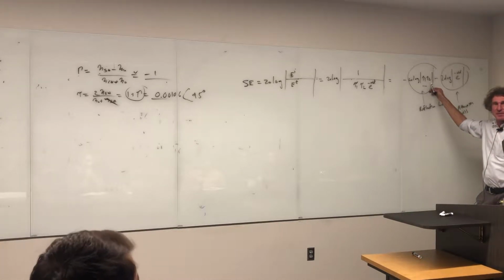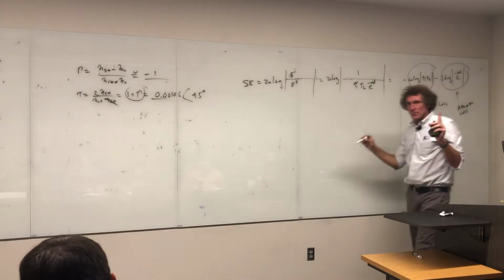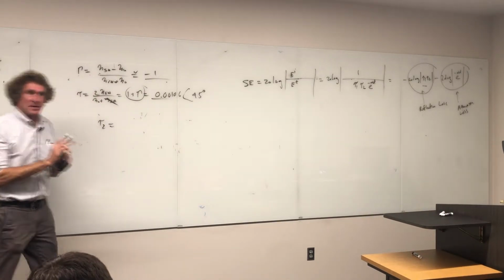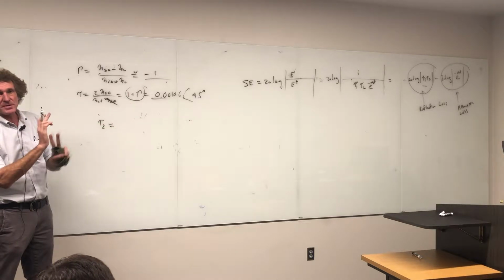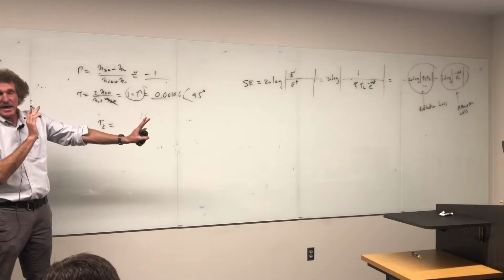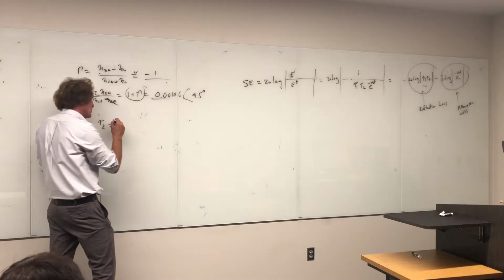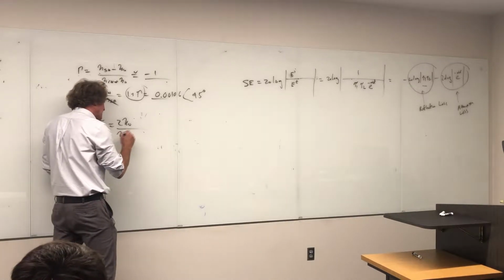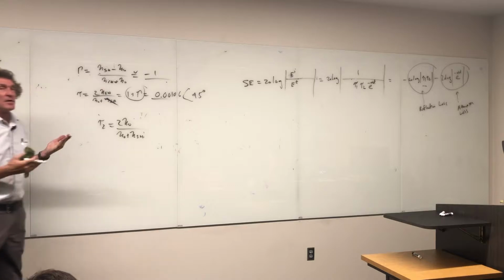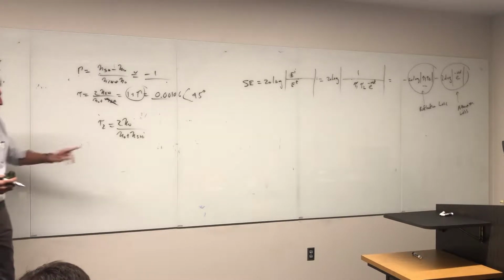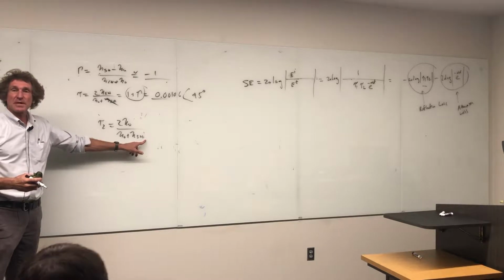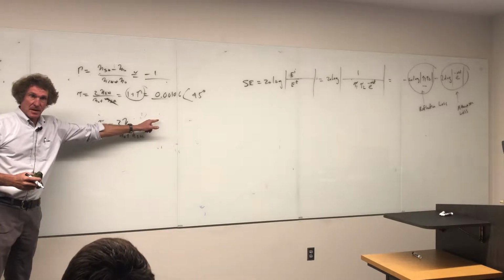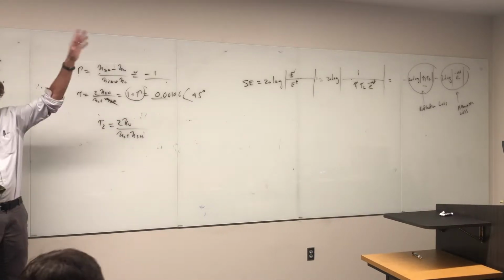Now, do you remember, anybody remember what I said about tau 2? Well, the formula for tau 2, or tau anything, is what? It's always the impedance you're going into. This is when you're in the shield, you're coming out of the shield. Well, what impedance am I going into? Right, eta naught, right? So it's going to be 2 times eta naught over what? Anybody? Eta naught plus eta shield. For either reflection coefficient or transmission coefficient, the bottom stays the same. If it was reflection coefficient, it would be equal to eta naught minus eta shield. Do you follow me on this, class? We don't want reflection, we want transmission. How many understand that right here?